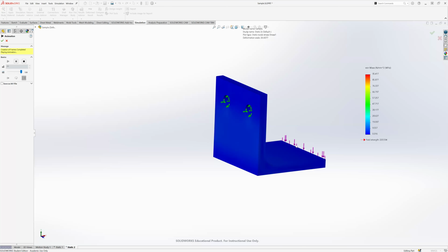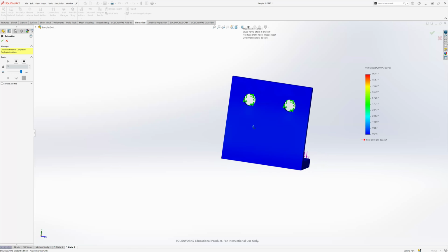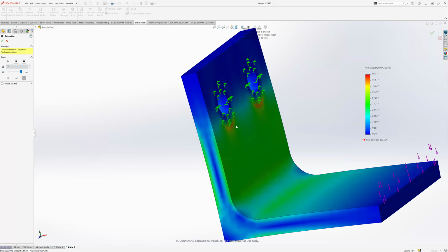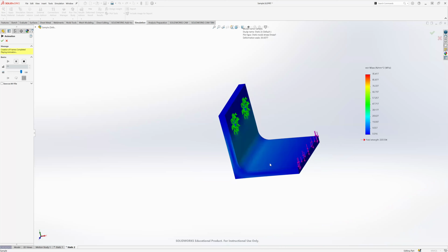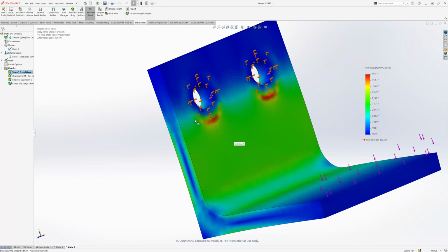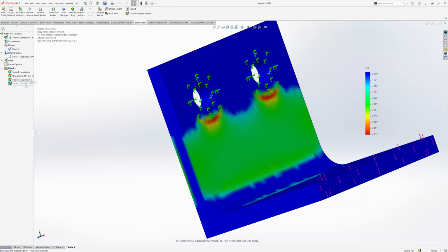Because the load, a lot of times, is just that this is sitting on this or it's supporting this amount of weight or whatever. But when you're dealing with fixtures, you want to make sure your fixtures are right, especially if you have something that's bolted. Because now, if you notice here, I don't have any stress concentration here anymore. If I get out of this, my stress concentration now is right here.